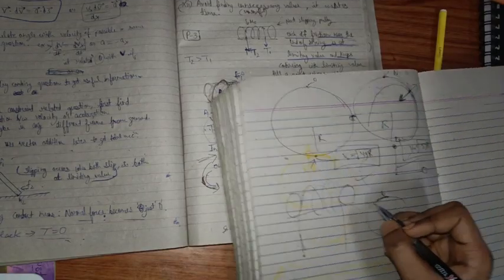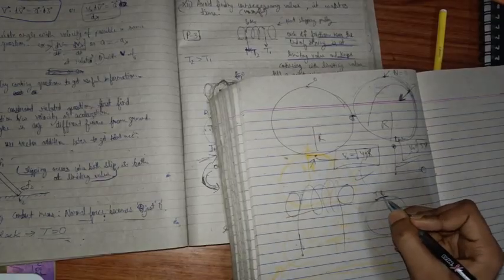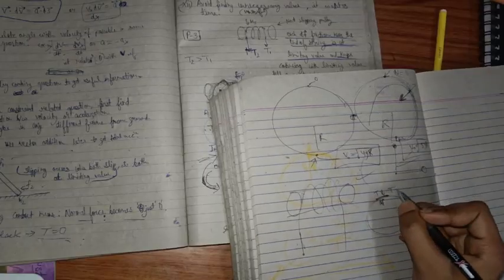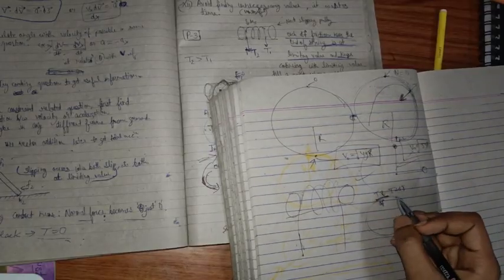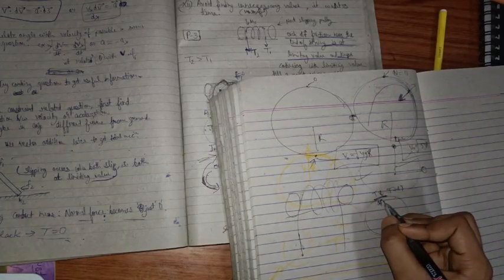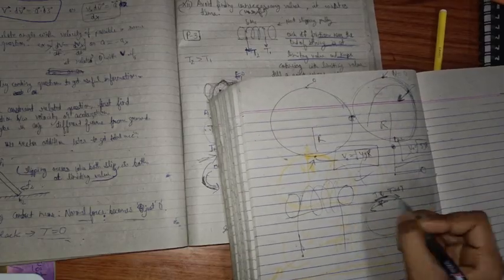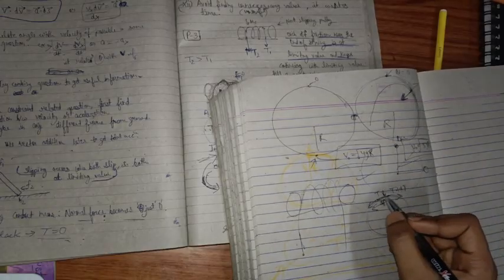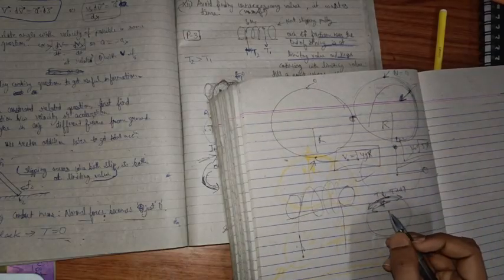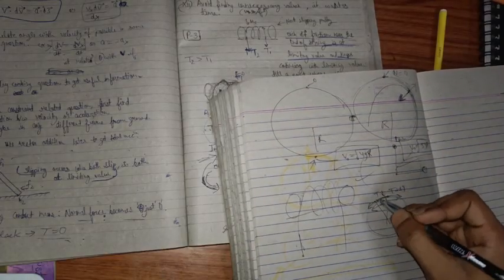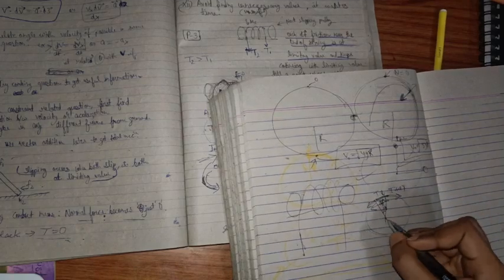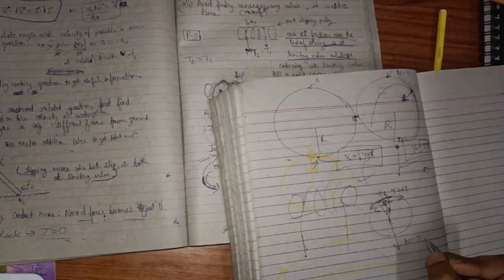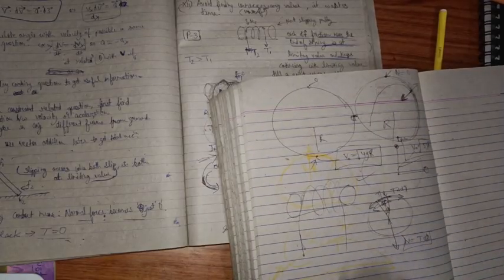At any point, let's say here, the tension at one side is T, and due to friction, the other side will get some T plus dT tension. Due to this friction, let's say friction is acting in this direction and it is pulling in this direction, so the dT is the tension at this side more than this side. In this case, because this is a curved path and this is, let's say, d theta angle, then this will apply some force in this direction, which is called the normal force. That would be equal to T d theta in this case.